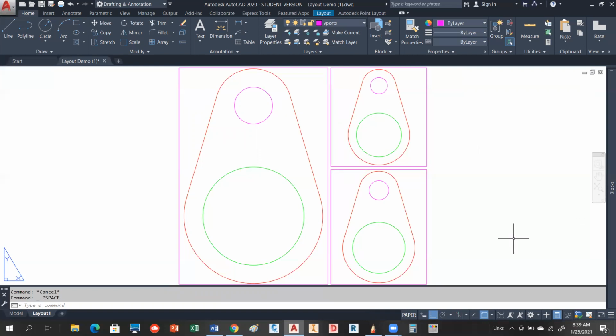So I got kicked off for just a minute. So at the beginning of this was all through the MView command, which is in your paper space to be able to see your model. Is that right? Well, yeah, what it does, it allows you to create a model space viewport, right? So keep in mind what you're doing is you're actually creating an object here, okay? Are you following me? Yes, sir. And you are using MView, correct?